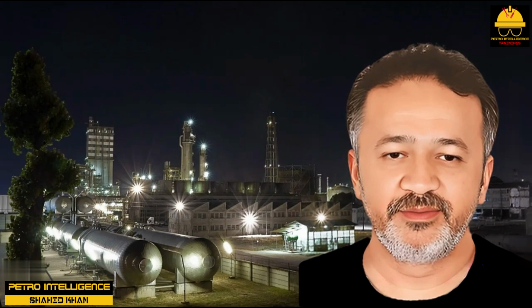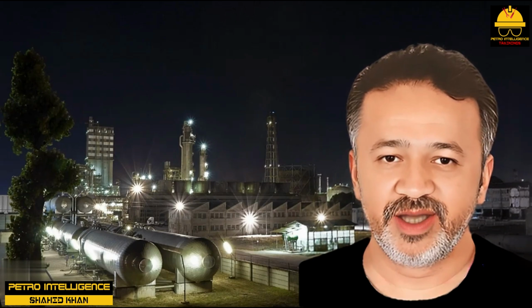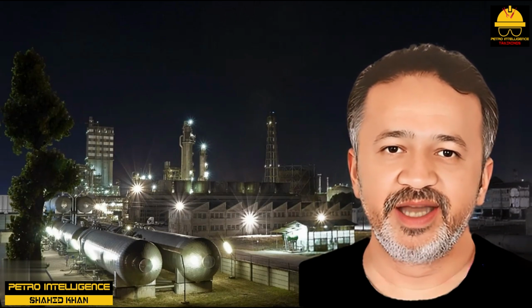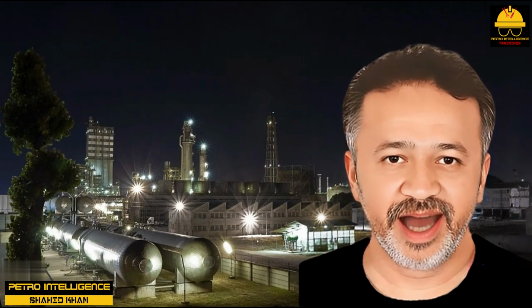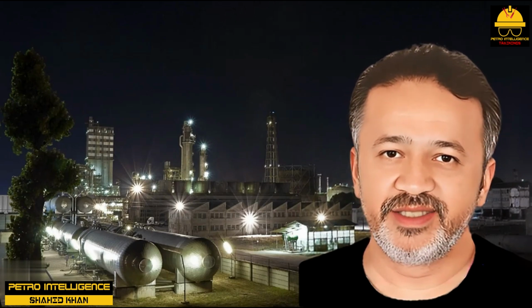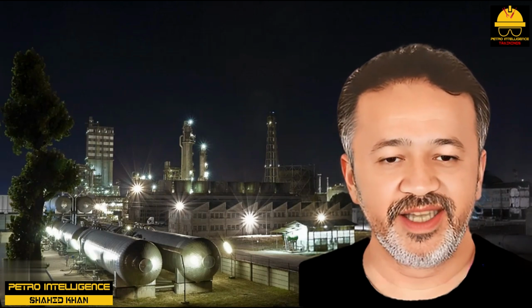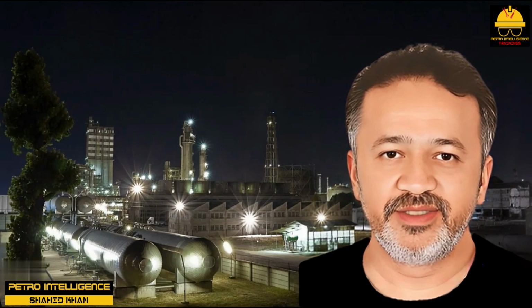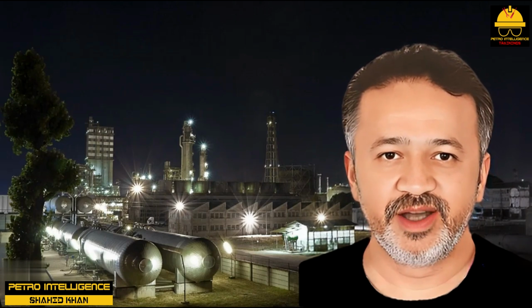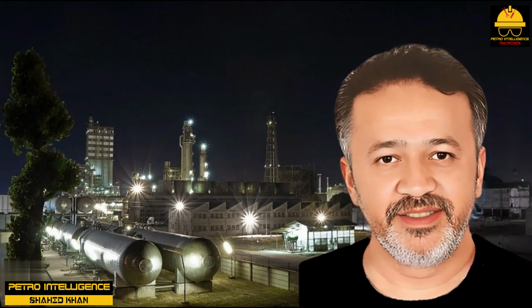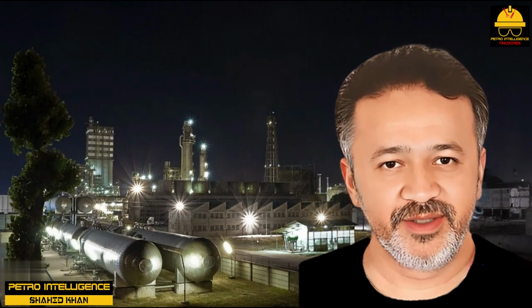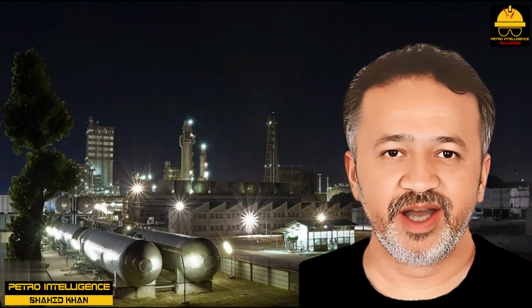Sweetening. This is a slightly exothermic process. Mercaptans are converted to disulfides by adding air. The catalyst is a blue powder, Merox, which impregnates a bed of charcoal saturated with caustic. Converting mercaptans to disulfides reduces the bad smell of gasoline and jet fuel. The process takes place at about 100 degrees Fahrenheit.